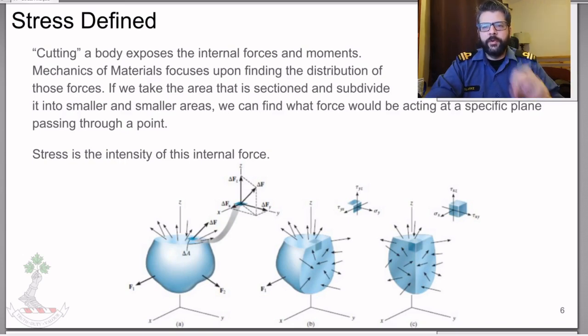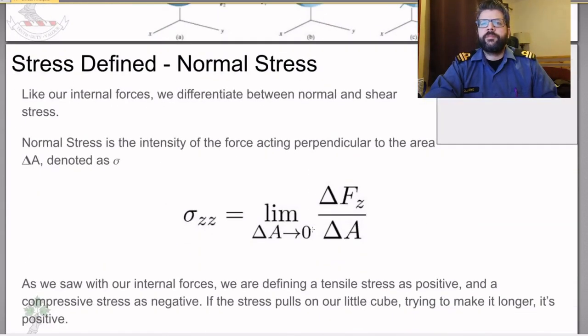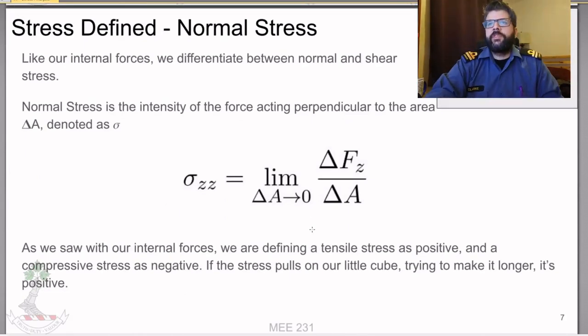the spots where we get the most force acting upon a tiny little spot, and we'll call that stress. Stress is the intensity of this internal force. We often conceptualize this by taking a cut, taking another cut, taking a bunch of cuts, and analyzing the stress at a tiny little section. But we'll talk about the two different types of stress that we're worried about.